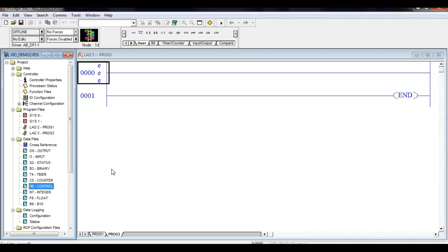We won't be dealing with those this semester. Integers, what's an integer? It's a whole number, right? This PLC only supports signed integers. Most of your newer PLCs, to give you more numbers, support both unsigned integers and signed integers. So an unsigned integer would be without a sign, so everything's assumed to be positive. A signed integer, we can have negative and positive.